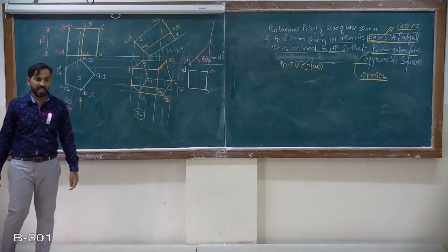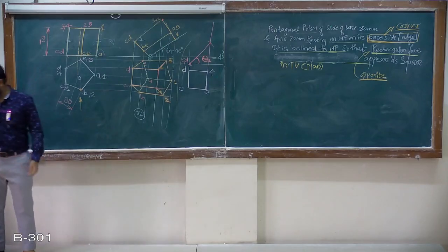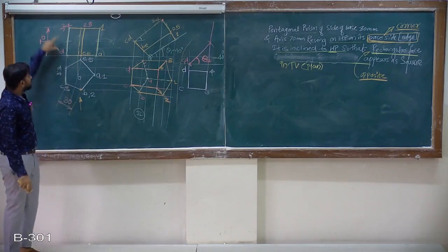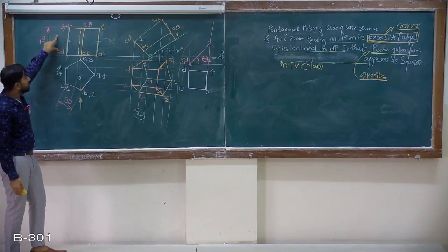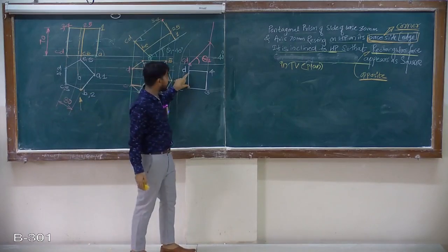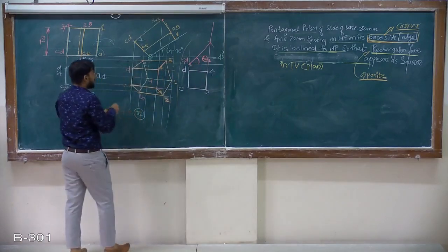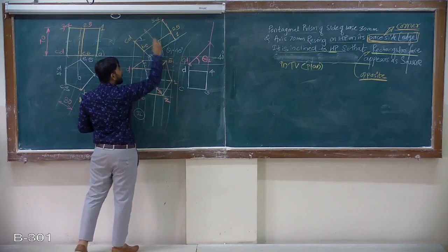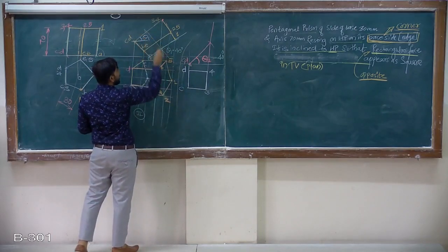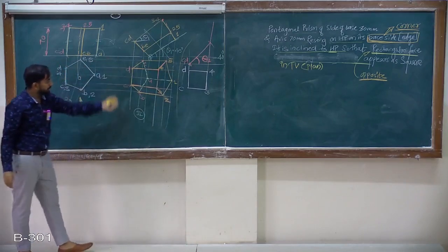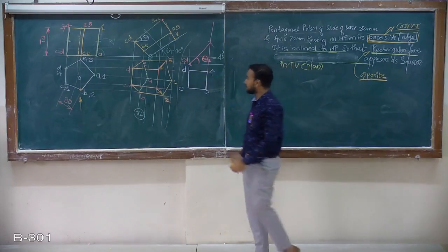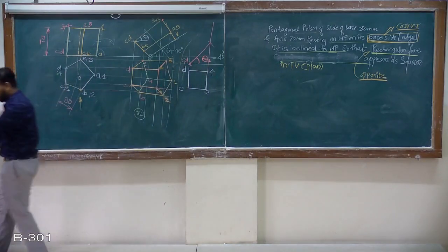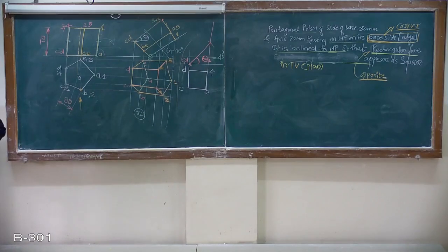That's it. This is a complete second stage top view when the opposite face appears as a square. So whenever the opposite rectangular face appears as a rectangle with any dimension, or maybe a square, first you construct the dimension as a square, find out the angle and take that angle for this edge, because as they are parallel, the angle made by this theta 1 and this theta 1 is the same. Then copy the view and you will get the second stage top view. This is for a pentagonal prism.